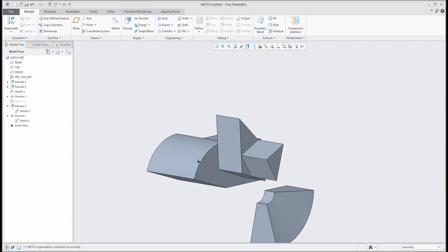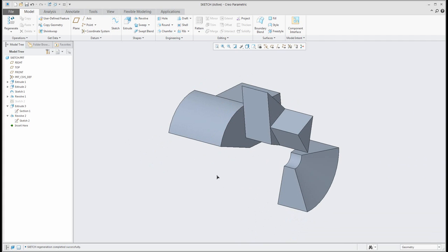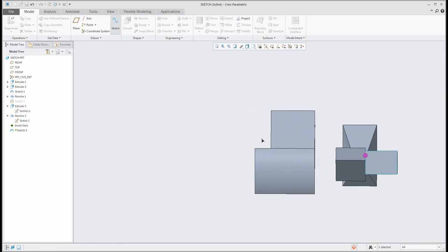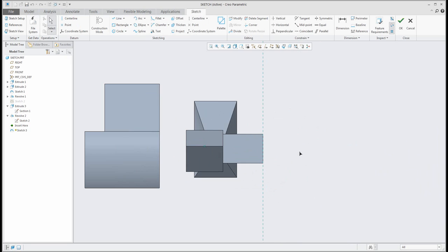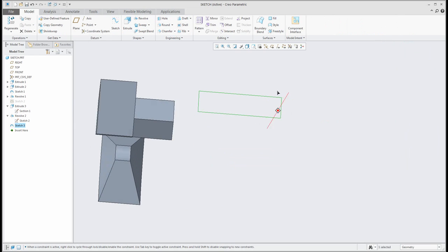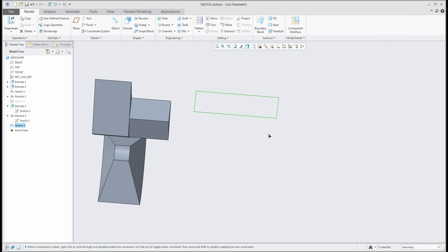And what about other options if you need to check whether your sketch is okay? If you create an outside sketch and make some mistakes, for example, you would like to create a corner rectangle, and then you create another line on top of this line. You can see it a little bit because over here are the red points. But if you confirm OK, it's no problem. The sketch is fine, but you know that the sketch has some problem.